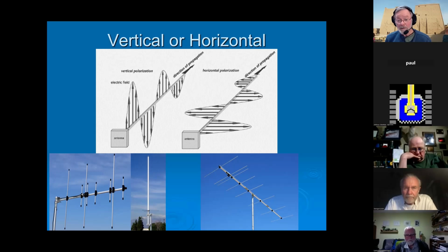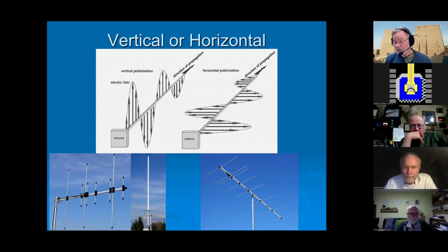The diagram shows vertical polarization, how it's coming in on that antenna. The antenna on the right-hand side is oriented in a horizontal direction, so it's going to perform best when everything that it's talking to has horizontal polarization.